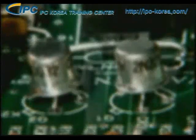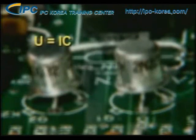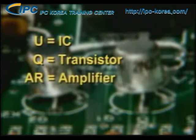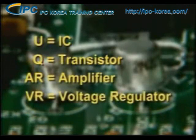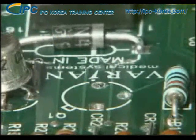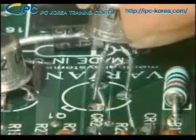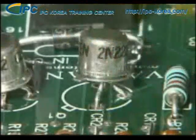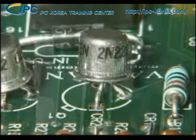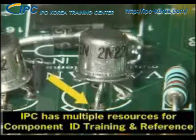Typical reference designators may include a U for a general IC, Q for a transistor, AR for an amplifier, or VR for a voltage regulator. IC cans contain a tab located over the highest numbered pin or between the highest numbered pin and pin 1. When you look down at the IC can, pin 1 will be located to the right of the tab.